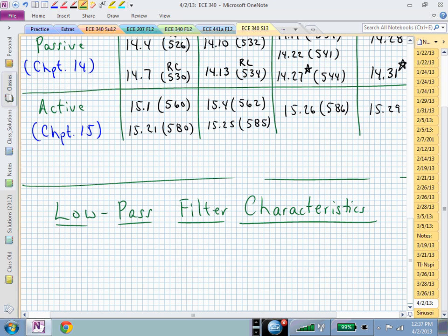And there's a little discussion in the book about second order filter parts. And if you're building up filters, you'll probably want to factor your denominator into real and complex factors and realize a second order and a first order combination and put those together.